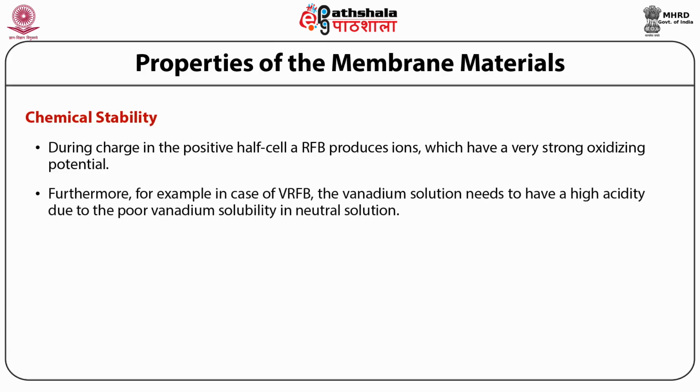Furthermore, for example, in the case of VRFB, the vanadium solution needs to have a high acidity due to the poor vanadium solubility in neutral solution. The membranes applied in the vanadium redox flow battery, or VRFB, need to be chemically stable at these harsh conditions.